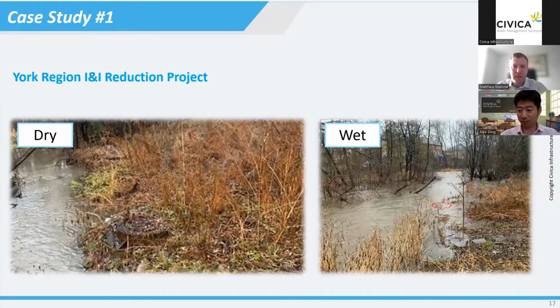All right, thanks, Alex. Piggybacking on what Alex was saying there, you were talking a little more theoretical at a point there with the pipe and the groundwater. There have to be these defects and the groundwater interaction, and that's a conceptual model of what happens during wet weather. But then looking at some of the results, that last slide showing pipes and manholes where we had investigated during dry weather and hadn't seen anything, and then gone back during wet weather, it's a totally different story.